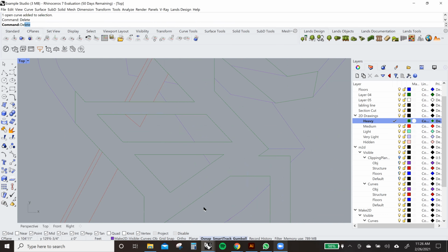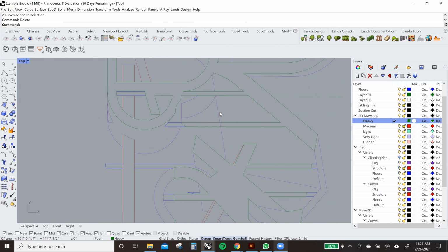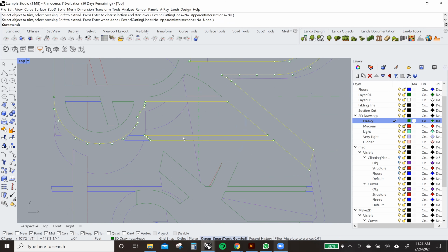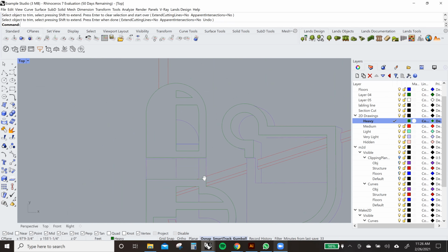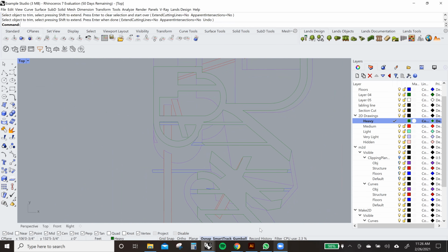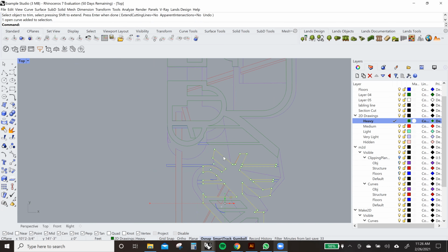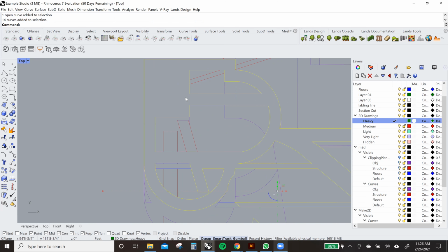Okay, so that's more or less cleaned up. Something you can do is, and I think Sam's basically done here, but as you're doing this process, zoom in at the top of your model and work with the cut line selected in yellow. You can work your way all the way down the project looking for anything that's inside of the yellow, slowly and methodically. It's a lot better than jumping around the project looking for things that you missed, because then your eyes aren't focusing on anything particularly.